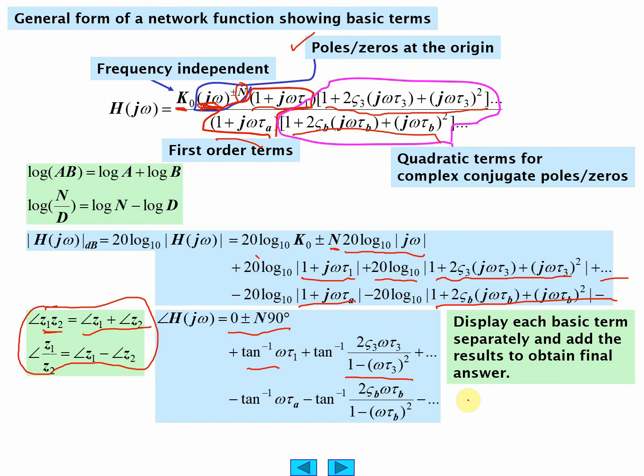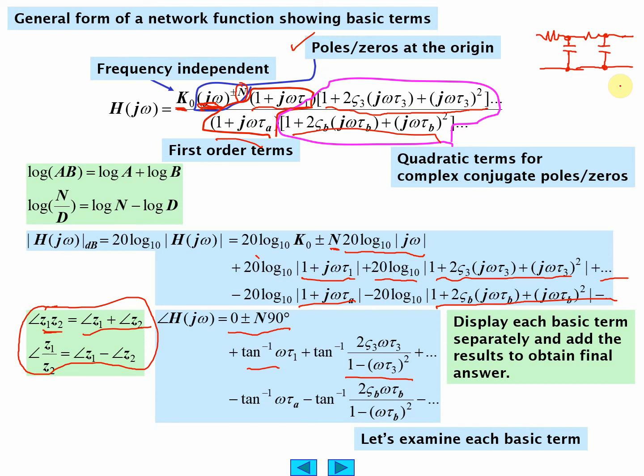We use the continuum approximation, so it can go to infinity. We consider each little piece of the cable as a resistor and a capacitor in series, and model it like this, just a zillion little things. So we do use continuum approximation to analyze continuous regions. Like this is an example of a coax cable. Okay, there's so much resistance per foot and so forth.